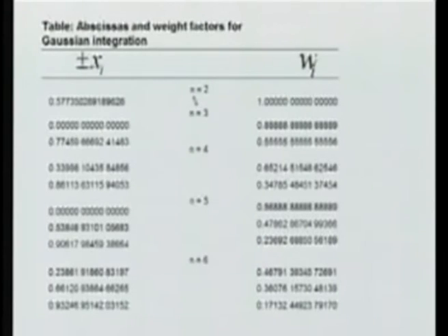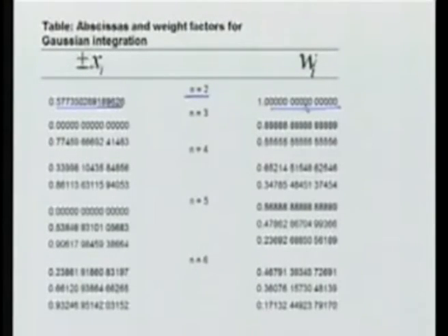You see that if I have the 1 point rule, there was nothing big that had to be done. The location is psi equal to 0 and the weight is 2. If I have the 2 point rule, here I have 2 points with plus minus psi as my coordinates. So, these are the symmetric points and the weights are this. And you see that here effort has been made, this has been borrowed from a book, to obtain the points with sufficient precision. So, up to 15 decimal places this has been obtained, and that is very important from a computational point of view, because we would like to do our computations in double precision, and if we want to do so, we should ensure that the Gauss points or the integration points that we have and the corresponding weights are also obtained in double precision. So, very nicely all these points are given here.